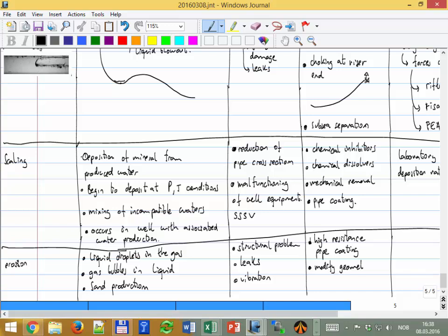You usually have these bends in jumpers and in connectors between the wellhead and the template, and that's where you can put these modifications. Also, one thing that we don't like too much, but that is very effective, is to reduce the flow rate. But that's really the last resort, and some fields just don't have any choice. They just have to reduce the rate.